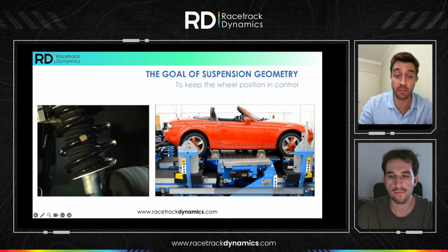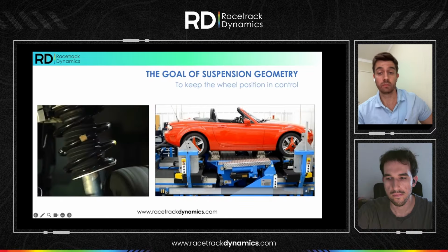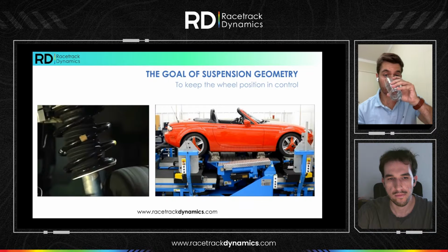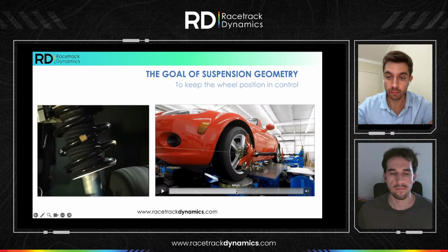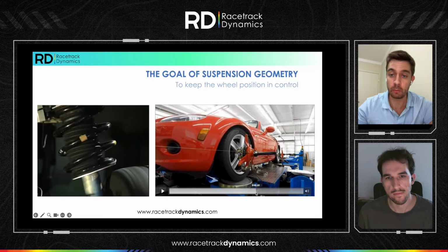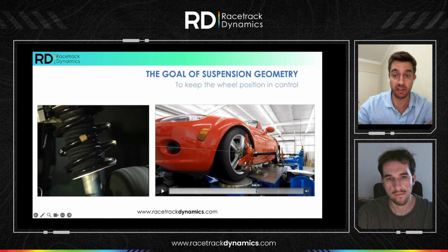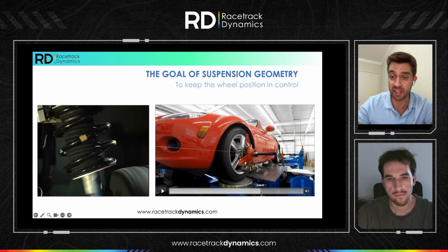And we're going to see that in a bit. Straight up and down within defined displacement bounds. During the bounce test, lateral and longitudinal forces and aligning moments are measured. Can you see the camber on the wheel? Can you see how, as we impose this vertical motion, the wheel is changing its camber angle, its inclination angle?